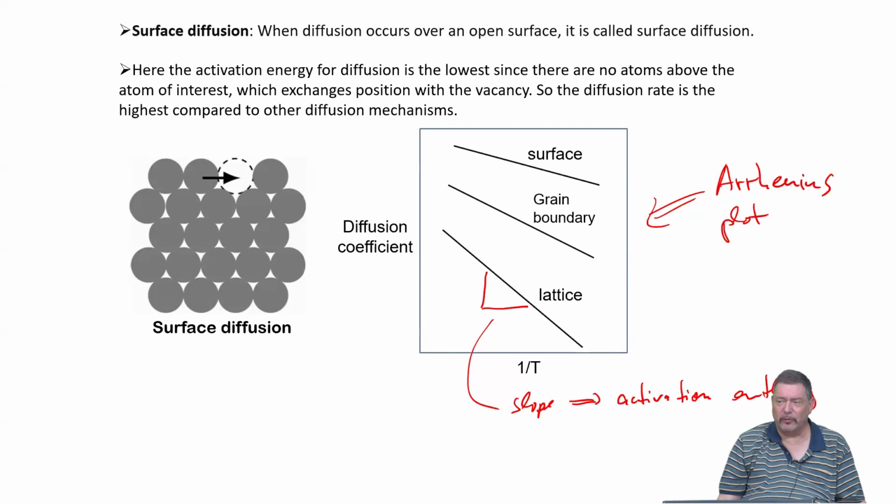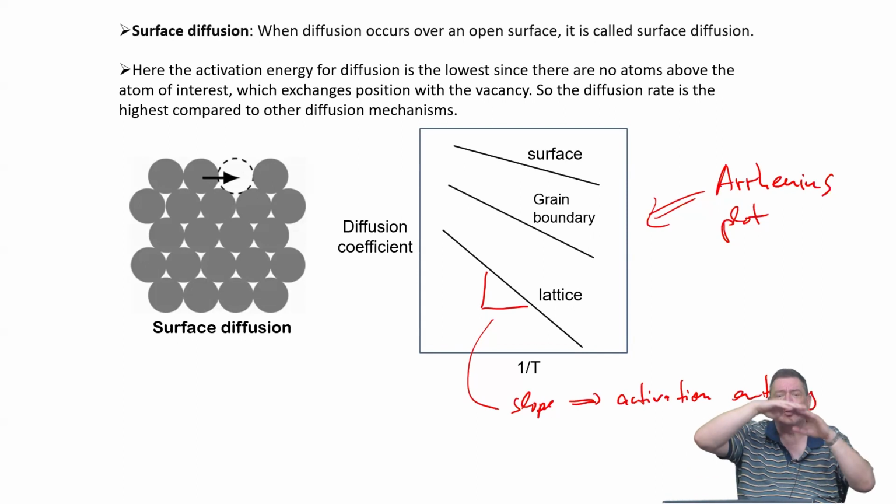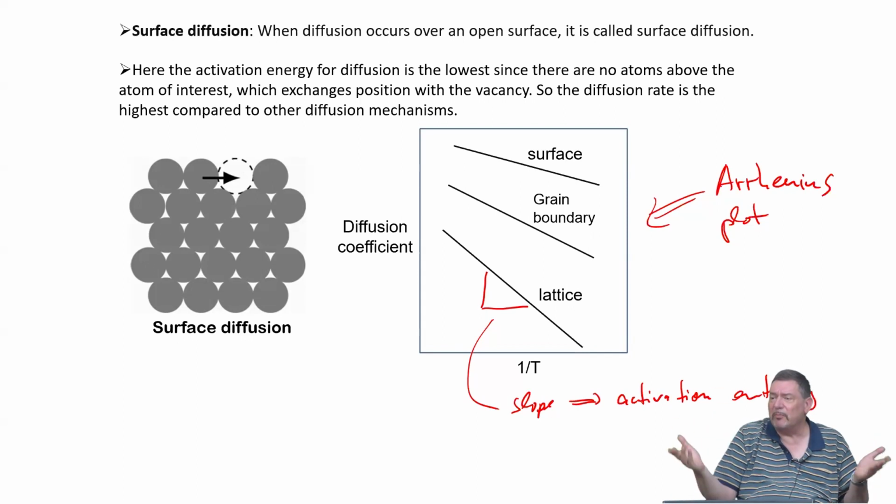But if you, for example, now make the time shorter and shorter, what will you do? You will freeze out the slowest diffusion processes because they cannot contribute much in this shorter time to the net overall diffusion flux, right? So the shorter the time at a certain temperature, the more dominant will be the outcome of the fast processes on the measured profile. And if you don't have the free surface included, then it will be grain boundary diffusion. Or if you wait a little longer, maybe also dislocation pipe diffusion.